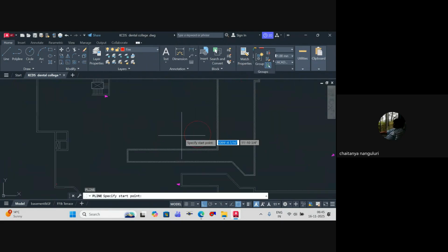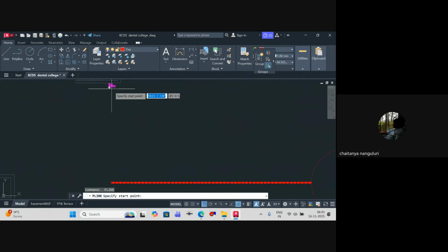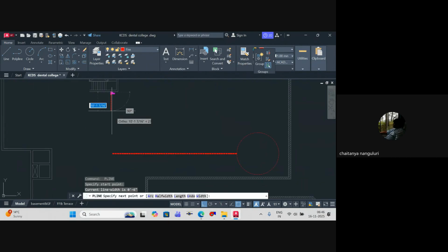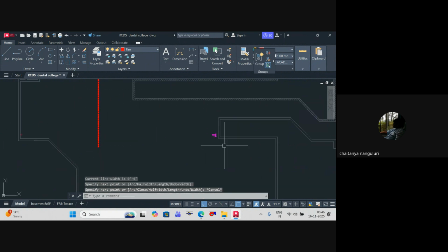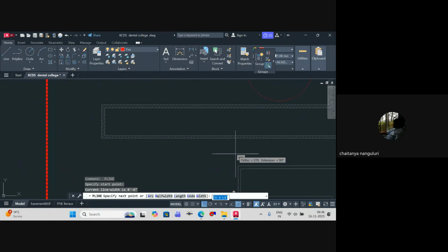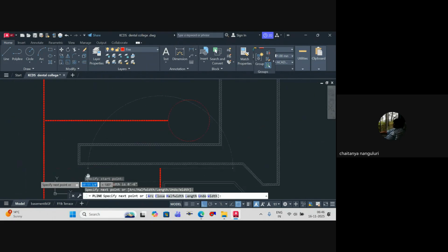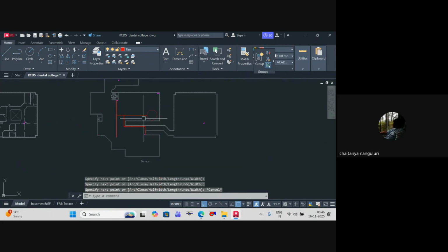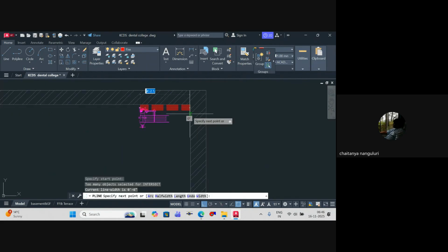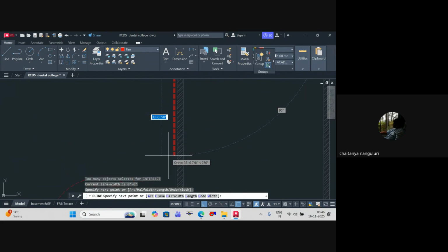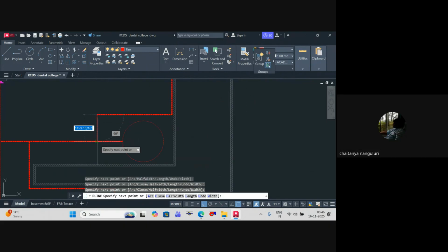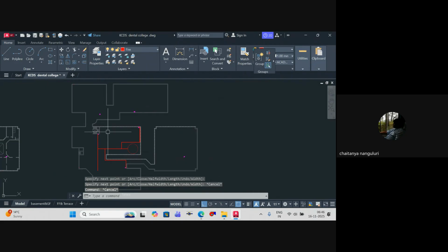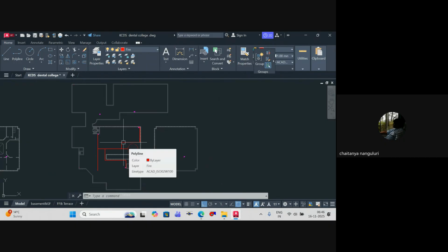Then what you have to do is connect all these hydrants to a terrace piping. Of course, you will take it peripheral, but as of now, as we're not constructing here, I'm just showing you. So we take it peripheral so that it is not obstructing people's path. Clear? Understood? Yes, sir. So we'll connect it to the hydrant system. All the hydrants on the terrace should be connected to your terrace piping, nothing else. I'll share a couple of drawings so that you can go through the entire drawing and understand all the sprinkler system and how we do it. Clear?